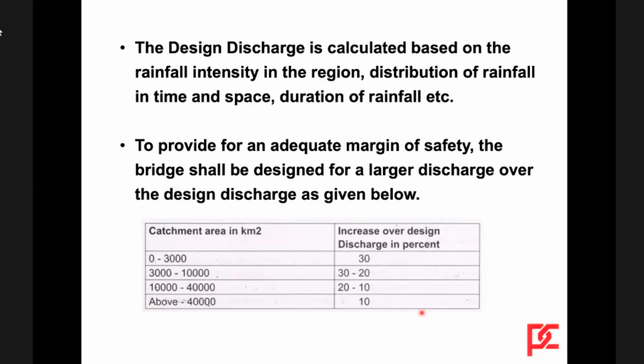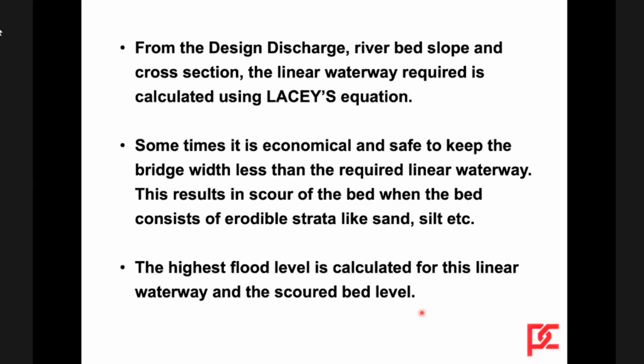For the design of the foundation, we need to increase the discharge by a certain percentage, which is given in the code. Then from the design discharge, riverbed slope and cross section, the linear waterway required is calculated using Lacey's equation. Sometimes it is economical and safe to keep the bridge width less than the required linear waterway.